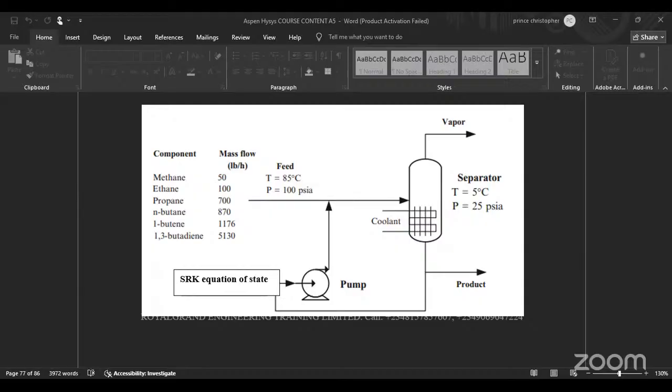I'm going to use a splitter here. Now this splitter is going to split this stream. We have another one here to pump. I'm going to name this to pump. Double click. My inlet stream is liquid. My outlet streams are bottom products and the next one is to pump.